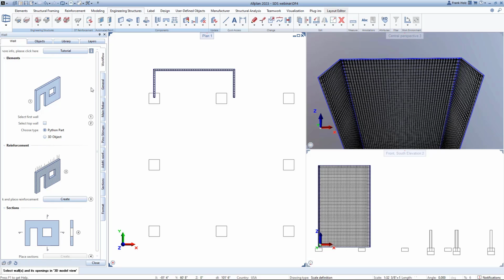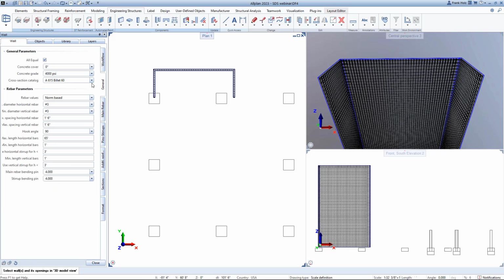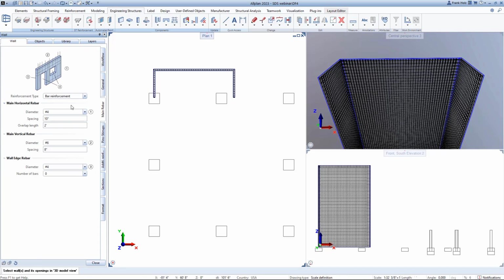We won't go into all of the attributes for all of the different apps we'll be looking at today. So I'm going to go more deeply in the first ones, and then we'll see that the other ones carry the same rhythm or workflow. On the General tab, we can set some basic rebar default minimum parameters, so minimum sizes, maximum spacings. And then on the next few tabs, this is where the designer is entering the information from the engineer. Those standards on the General tab could be industry standards or company standards, and if they're violated by the designer, they'll get a warning letting them know that something was below a minimum or above a maximum, and that they should possibly reconsider it.